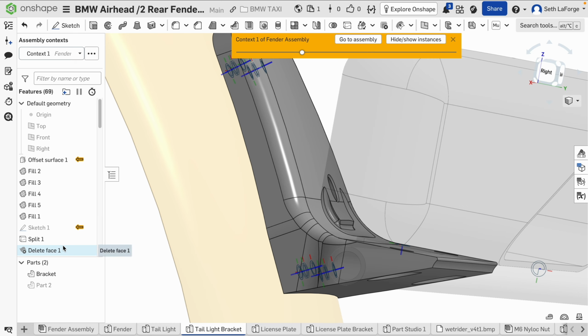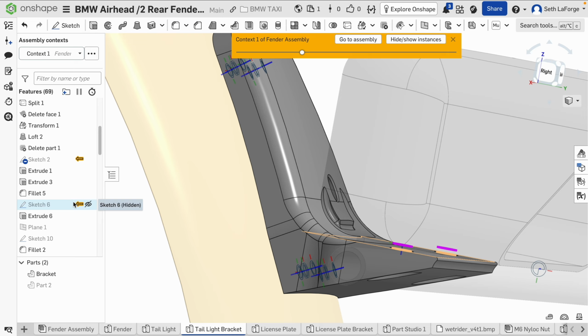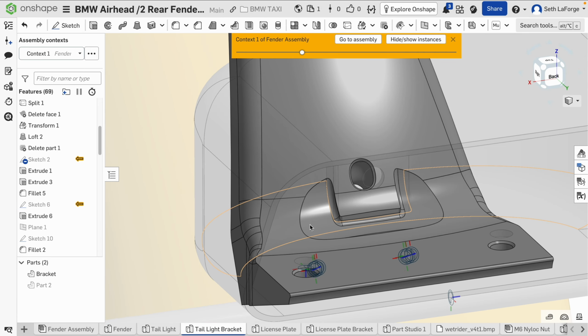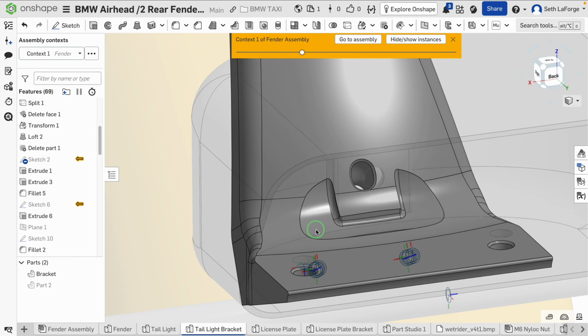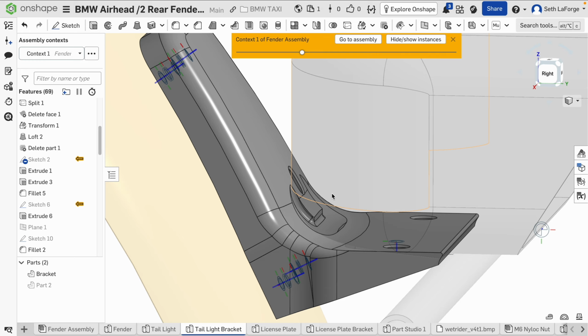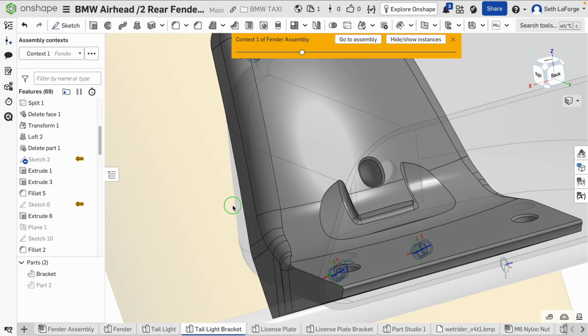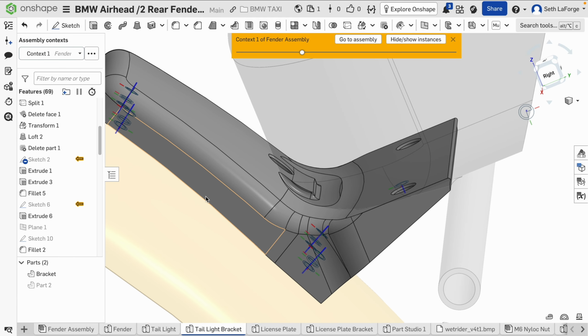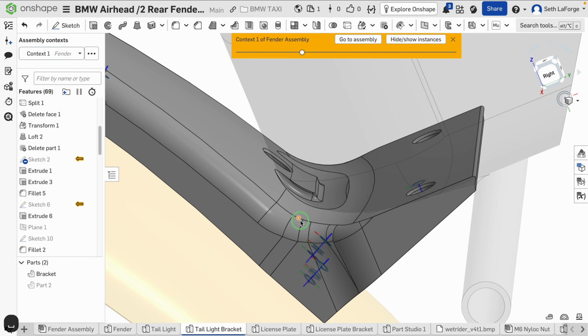And it's a little hard to show here, but notice that I had to hollow out an area on the bracket to fit this taillight. The first time I printed this, I discovered the taillight didn't quite fit because I had the shape wrong. And since, like in my previous example, that's a Boolean operation where I just subtract this shape from the solid that I'm developing,